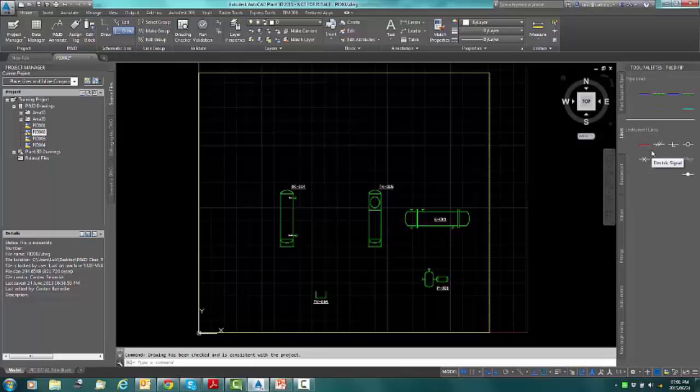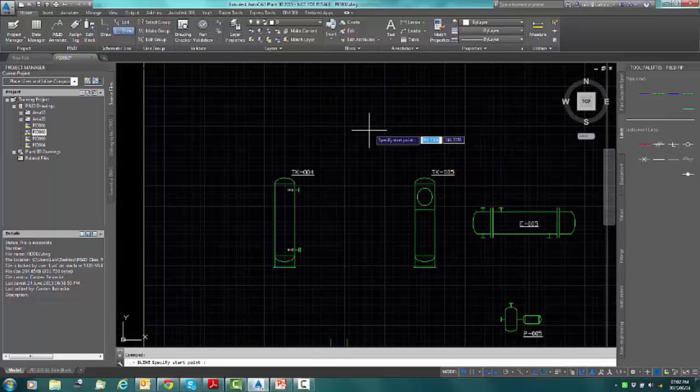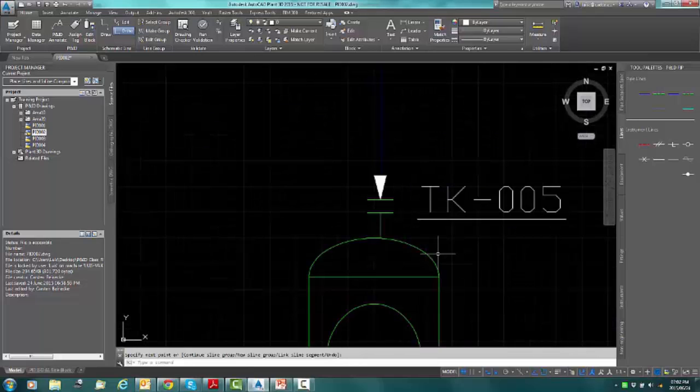Okay, so here we have multiple kinds of lines, and this is where some of the really cool stuff begins to work within PNID. So I want you to select a primary line segment, zoom in, and starting up more or less over here at the top, I want you to click. Use your snap tracking to get it right in the center over there. Click again and click on your vessel, and notice, look what it does. Automatically it adds a nozzle for you.